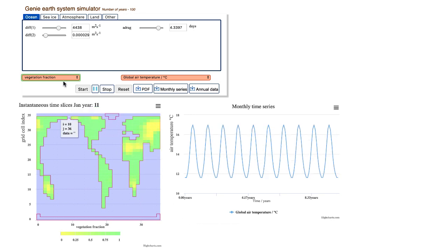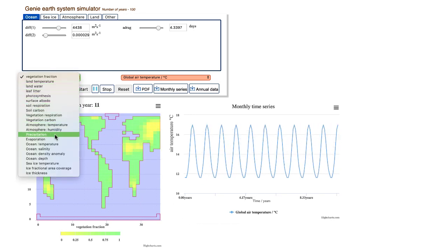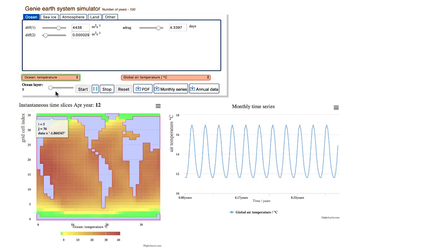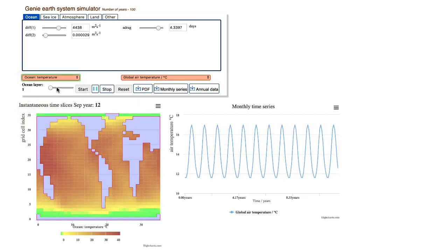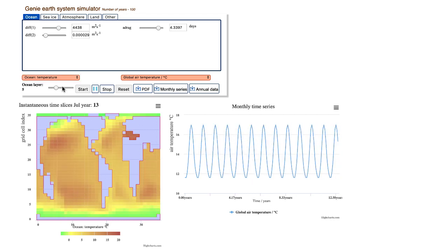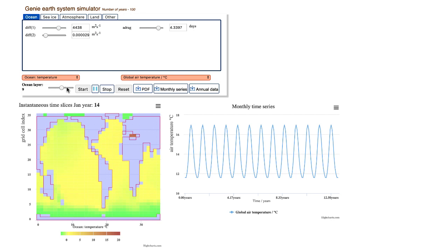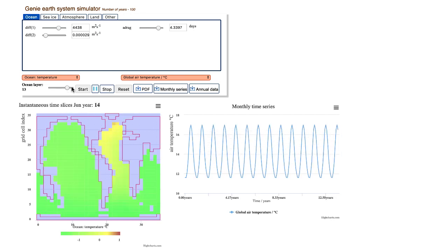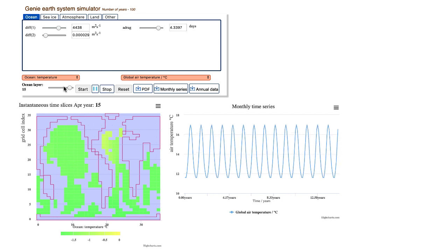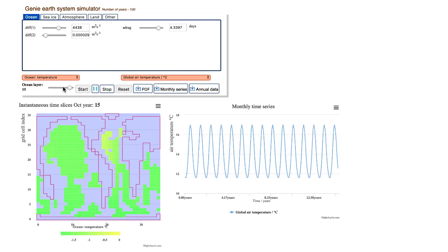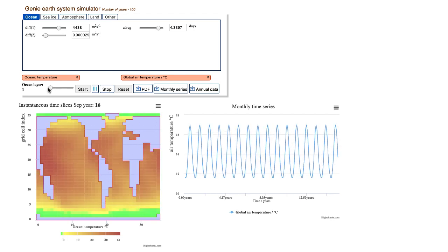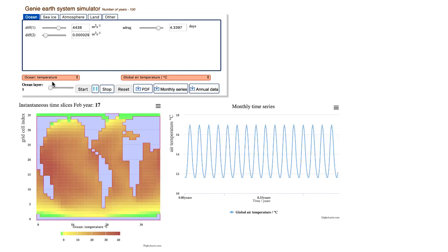If an ocean output is selected, you will be able to choose the depth level that is plotted. Remember that unlike the atmosphere, the ocean model in S397 GENIE is three-dimensional. These range from depth level 1, the surface ocean layer, which extends to a depth of 80 metres, to depth level 16, the deepest ocean layer, which goes to a depth of 5,000 metres. As you go to deeper levels, you'll see the ocean area shrinking, as not all ocean reaches these depths. The outline of the surface ocean is always visible.